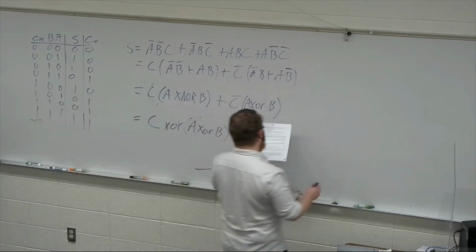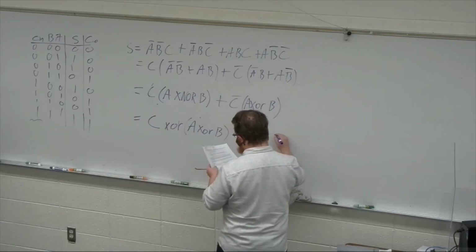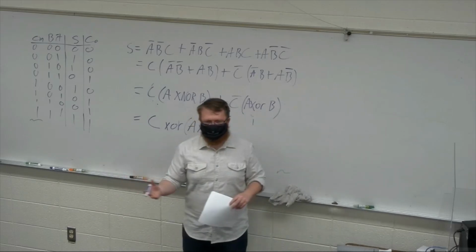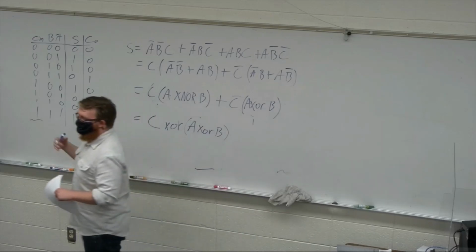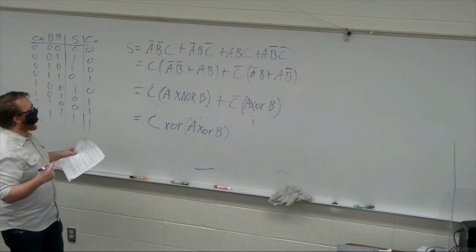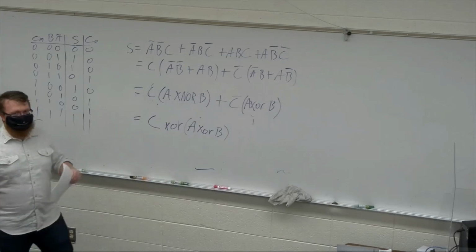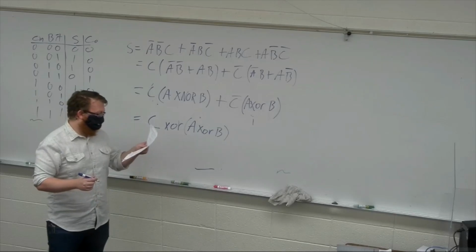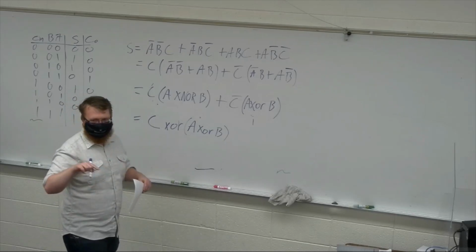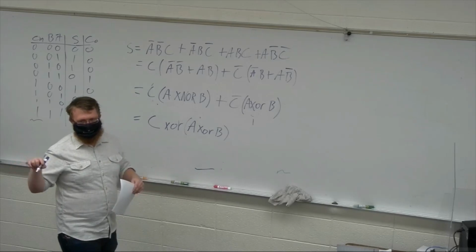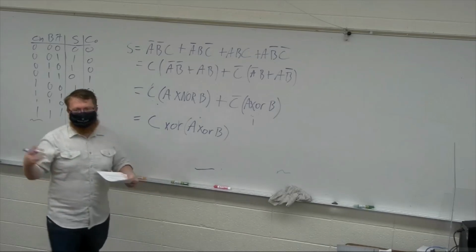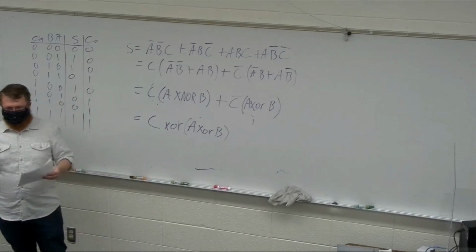We can do a similar thing where our carry out is really just, well, this is a trick that they're going to use. The carry out, right, is just going to be if I have A and B, if I use a half adder, right? Sorry, A and B, not XOR. The carry out is just A and B if I have a carry out. It's a little bit more complicated if I have a carry in, so it's a full adder. But we're going to use the fact that a half adder uses only A and B.